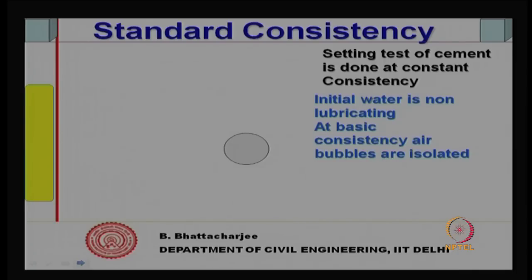Consistency is important. Consistency per se may not be as important, but then we do the setting test at a constant consistency. Now, how can you define a constant consistency? Of course, it was done initially empirically through a particular test, which we will talk about, but the water content corresponding to the standard consistency cannot really be defined otherwise, and therefore, at that consistency we do the test. Now, that consistency corresponds to basic water content as I mentioned, and consider